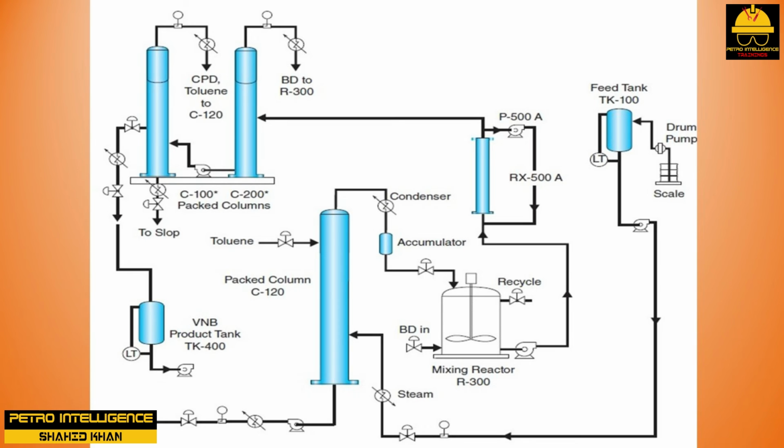In the continuous mixing reactor, chilled water coils maintain a low temperature. Butadiene enters the bottom of the reactor and mixes with the overhead distillate. The mixed feed is sent to a feed preheater before it enters the tubular reactor. The reactor resembles a shell and tube heat exchanger with 3 large tubes.